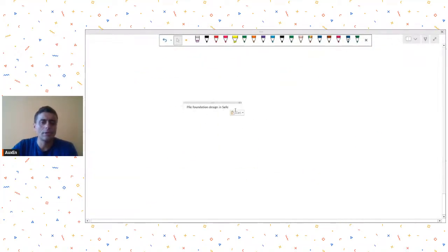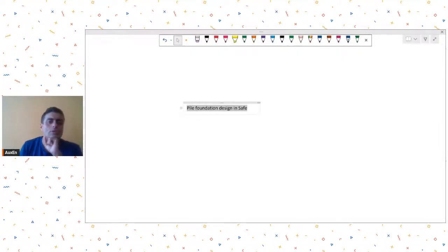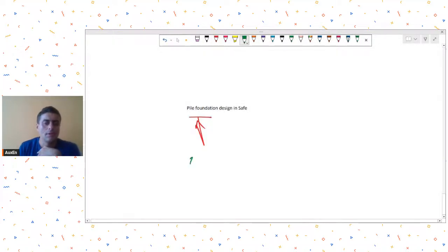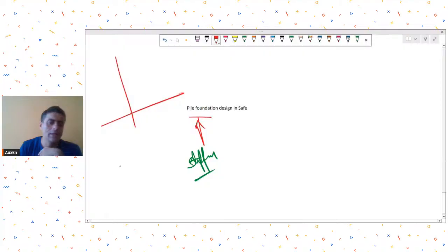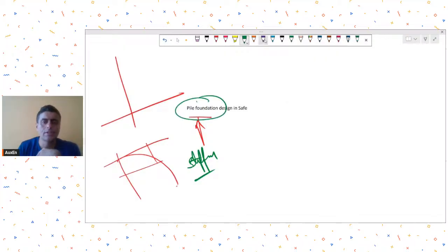First, you need to know the stiffness of these piles. This you can typically get from the geotechnical report, or you may have to look at the load settlement curve of your pile, and from there you could approximately calculate the pile spring stiffness. Once you know the spring stiffness, you make those points in SAFE, assign them the pile spring properties, assign them some size.